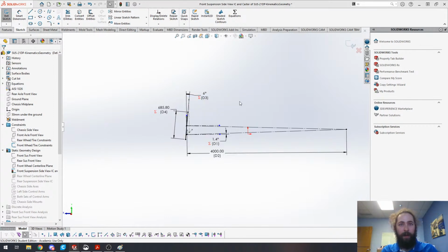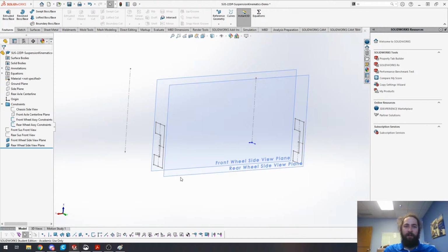Let's kind of go conceptual. So from the side view, the main things that are controlled are your anti-dive, anti-squat, and anti-lift properties. Those are all outlined again in RCVD. It kind of explains a few things about them, and it's kind of hard to tell what a reasonable value for a lot of those things is. And that all starts on page 617 onwards, section 17.3. It goes through all these calculations for calculating anti-dive. Couple things to keep in mind.